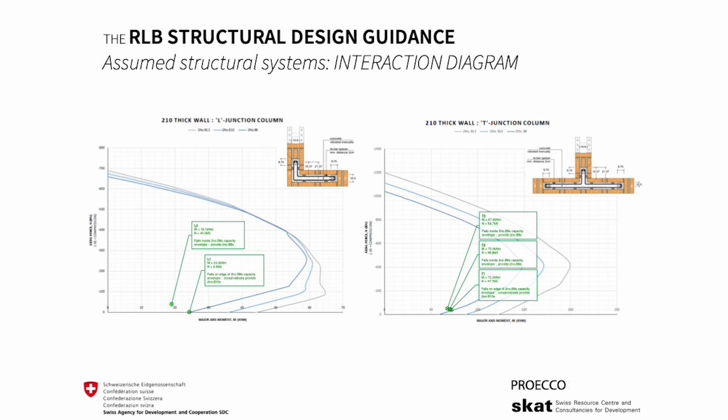A series of moment force charts have been developed for each of the element types. The combined major axis bending moments and axial compression forces are plotted on the relevant graphs to ensure they fall within the expected capacity envelope. Each moment force chart includes three different curve envelopes, which have been calculated based on different reinforcement bars, B8, B10 or B12, included in the vertical concrete pockets of each element. These different curves are used to select the reinforcement requirements for each member.